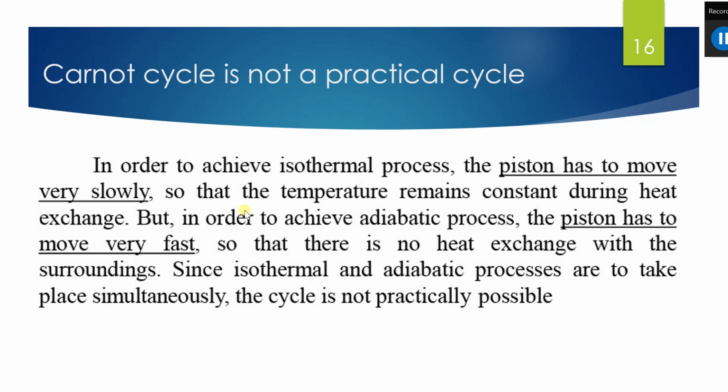But in order to achieve an adiabatic process, the piston has to move very fast, because adiabatic means no heat transfer occurs with the surroundings, and if the system moves slowly, heat transfer occurs with the surroundings. To avoid that, the piston has to move very fast so that there is no heat exchange with the surroundings.